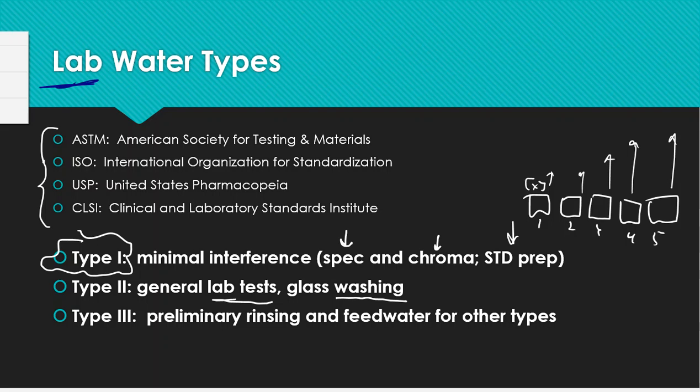that needs to be cleaned up. So again, CFPUA is taking the raw water, they're processing that a number of different ways. They are producing a product that's going through my tap in the laboratory setting. Well, that water is not good enough. That water could be type 3 because this is going to be used to then filter again with more sophisticated pieces of instrumentation and equipment to give me a type 2 or type 1 water supply. That is eventually what we are after in a laboratory setting.